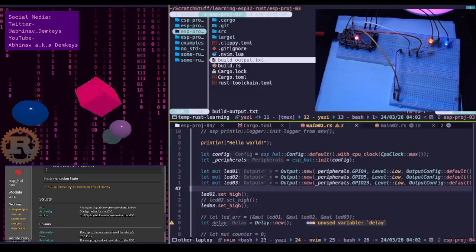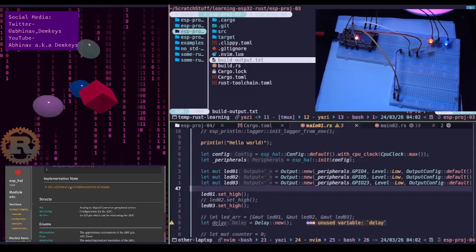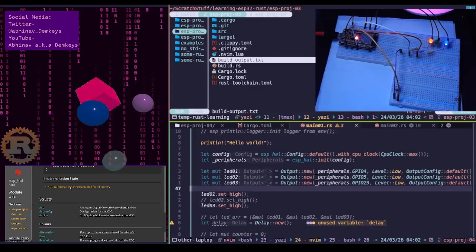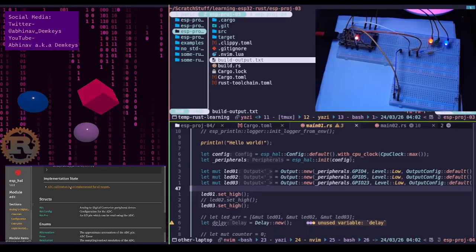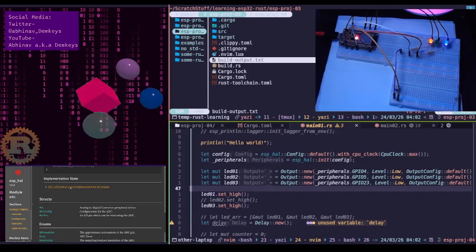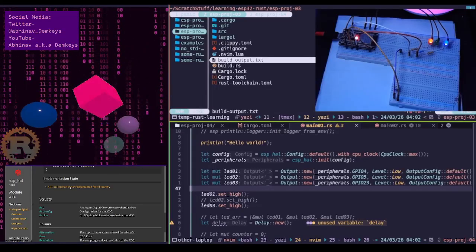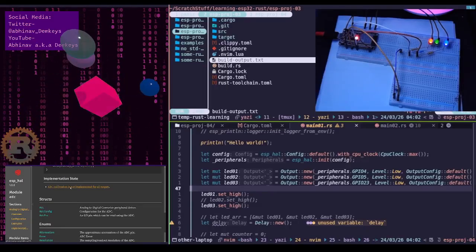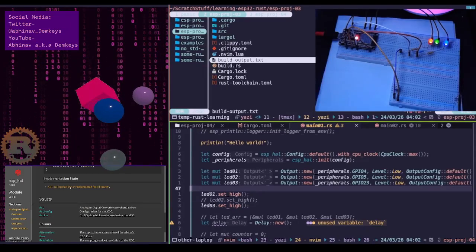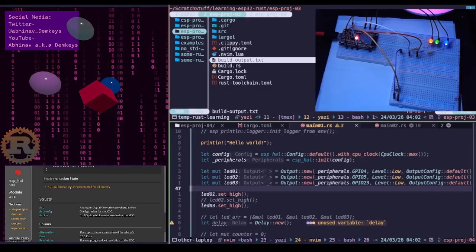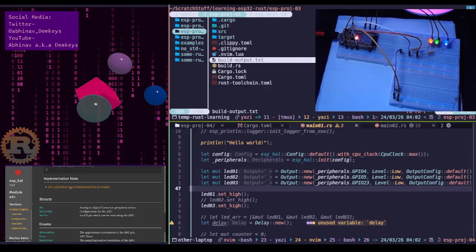So measure 0 volts, subtract that constant from all the readings. Measure the ADC reading at 0 volts. So we calculate what the offset would be, and then we basically apply that offset ourselves.